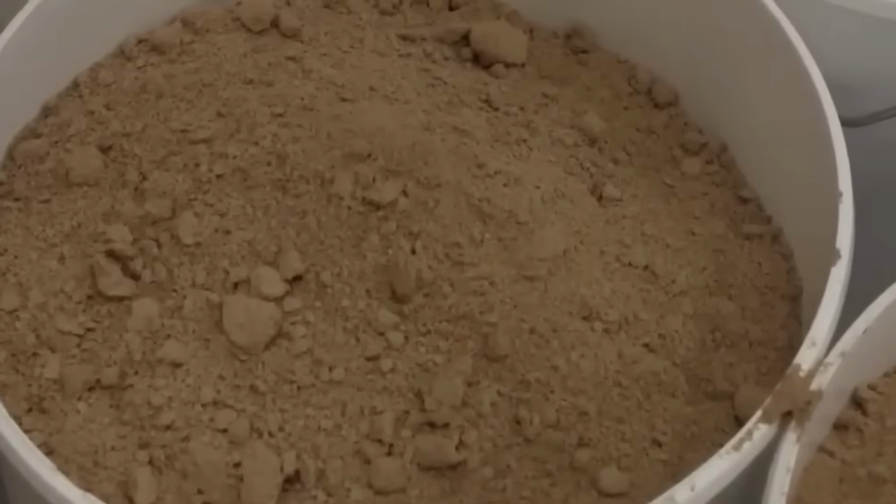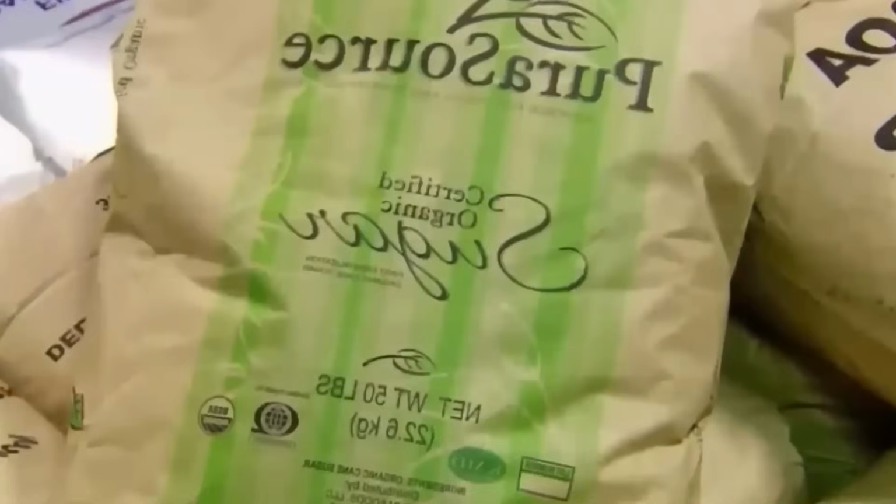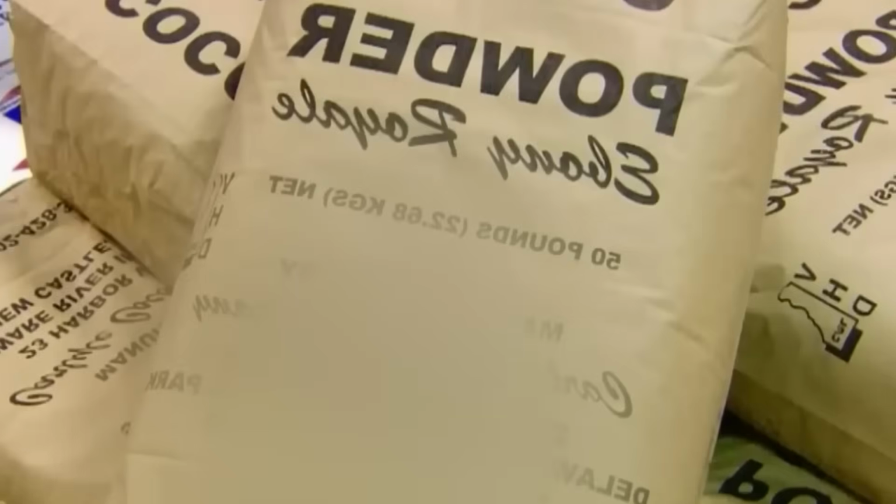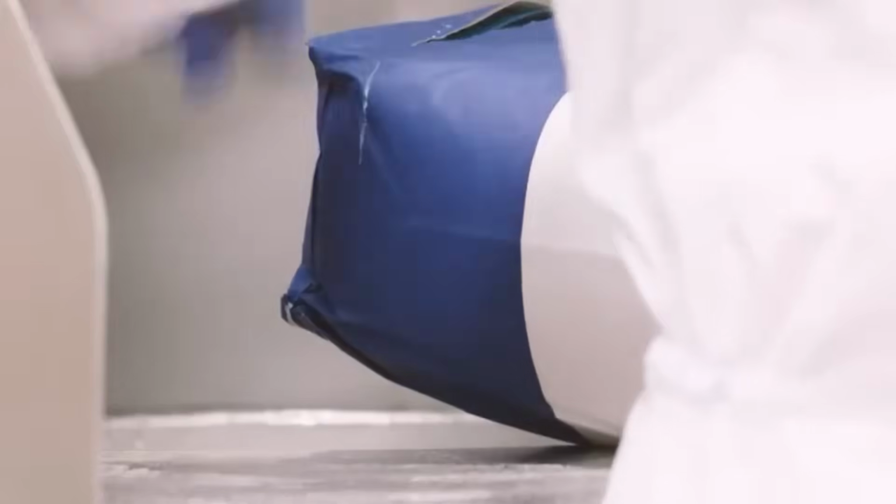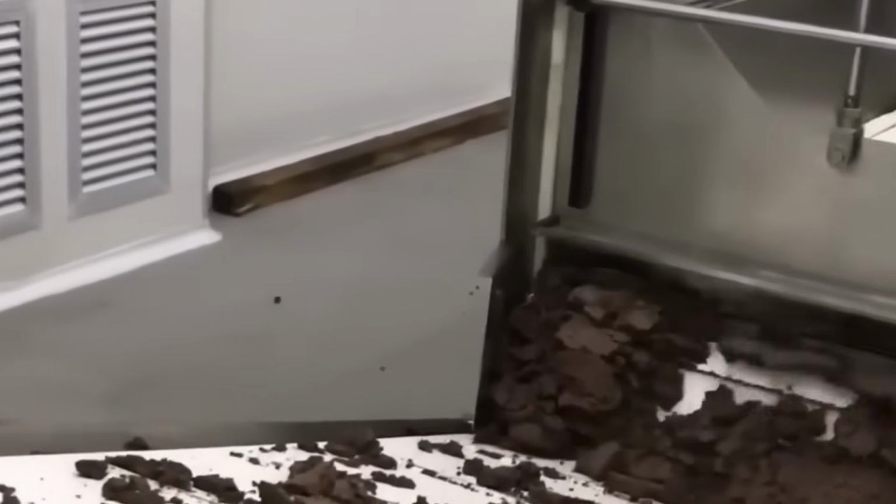Cleaning in place procedures are scheduled every 8 to 12 hours. Cream lines are flushed with heated water, followed by alkaline detergent, acid rinse, and sterile water rinse. Wafer production lines use dry cleaning methods for rollers and belts, followed by compressed air cleaning and manual wipe down of forming mandrels. Swab testing is used to verify microbial cleanliness, and ATP bioluminescence testing is used to assess organic residue. Production yield is calculated by comparing in-feed material weight to packaged product weight, adjusted for expected waste.